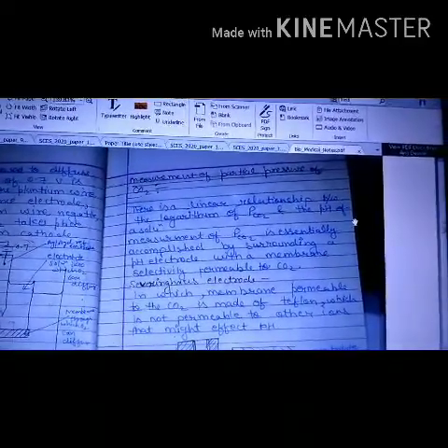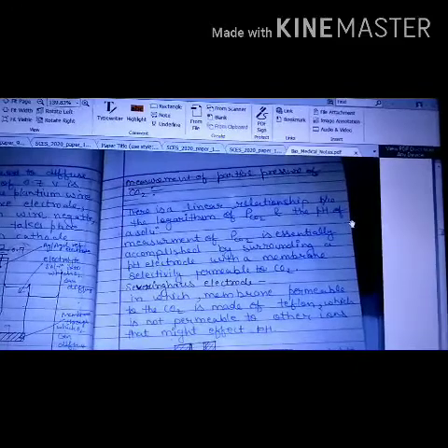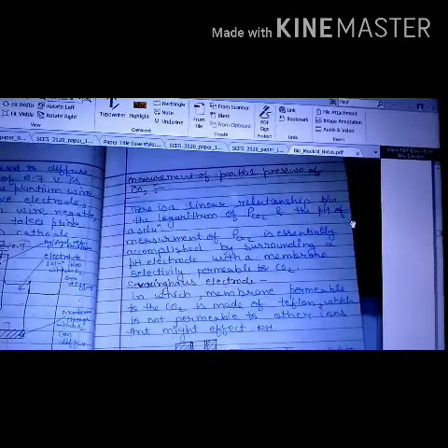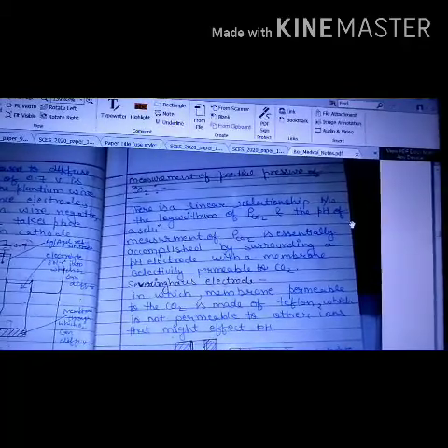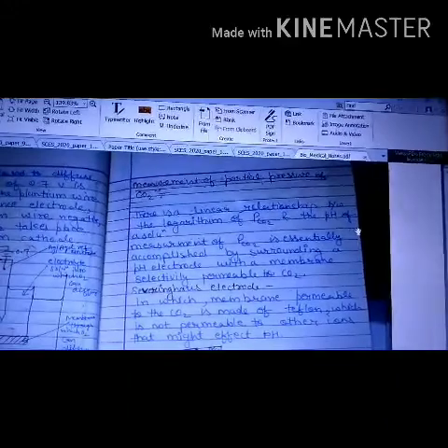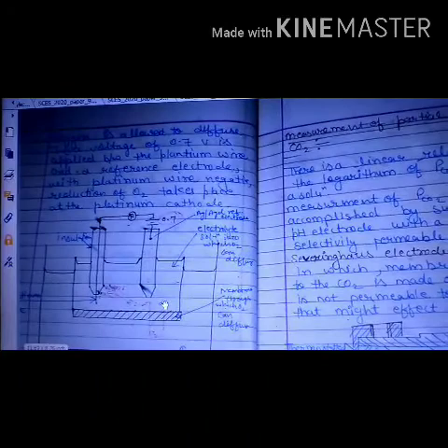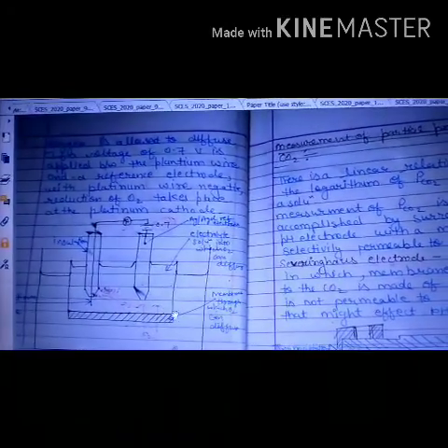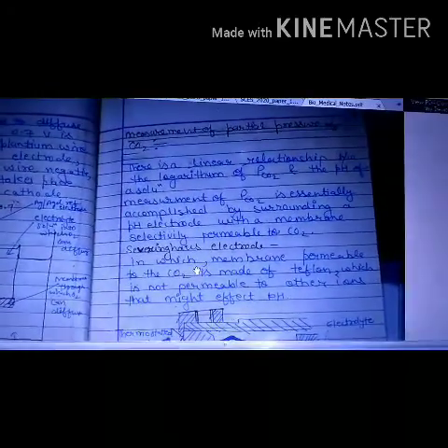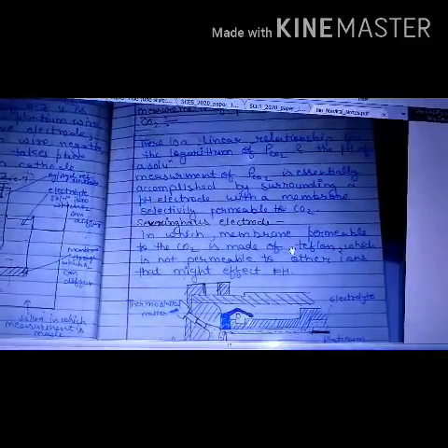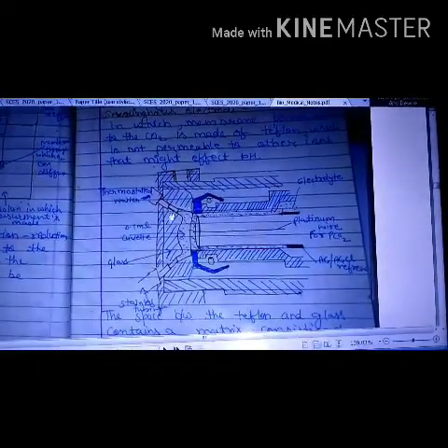Like in this figure we have a selectively permeable oxygen membrane. Instead of this we will be using a selectively permeable CO2 membrane. Then there is the Severinghaus electrode in which the membrane permeable to CO2 is made up of Teflon. Here is the structure of the basic arrangement for CO2 measurement, in which a semi-permeable membrane of Teflon material is used, and it does not permit any other ion to pass through it that might affect the